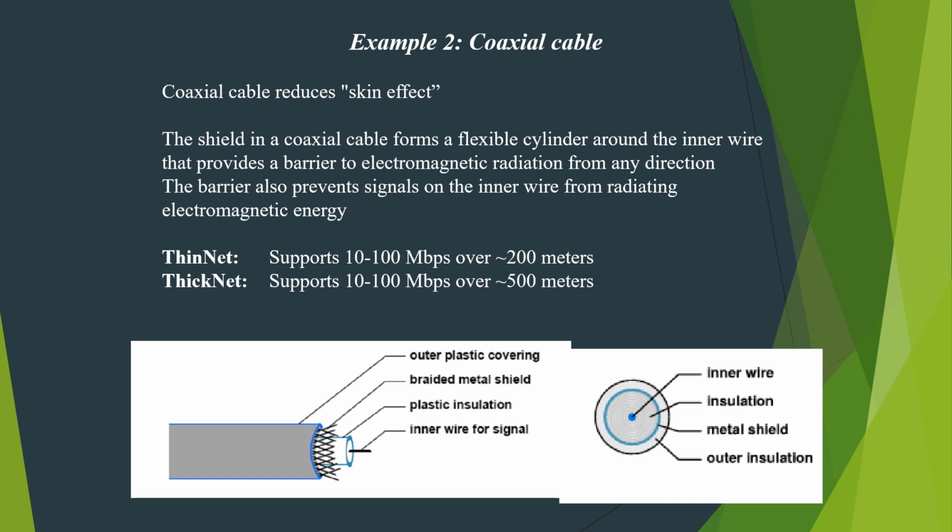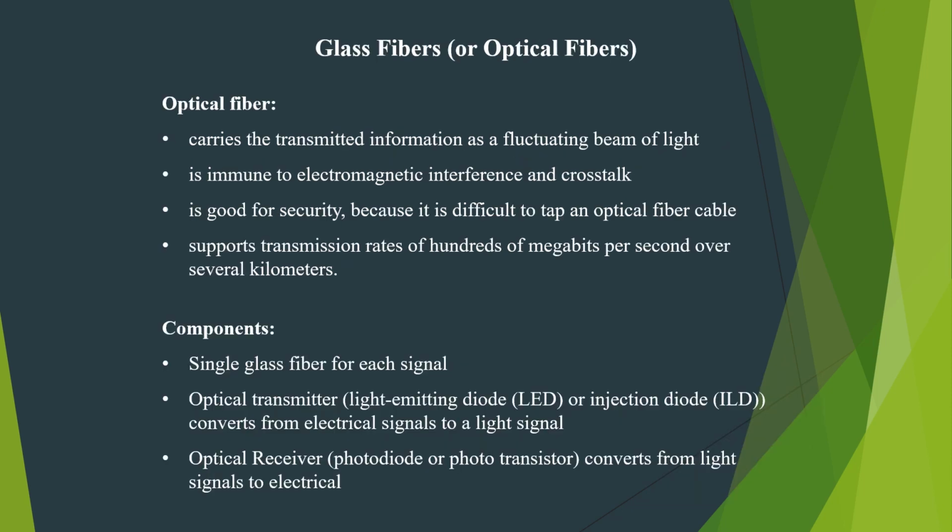And the disadvantages of coaxial cable are that distance is limited and the number of node connections is limited. Proper connectors and termination must be used. An application of coaxial cable is in analog and digital data transmission. We also use coaxial cable for telephone networks, Ethernet LAN, and in cable television networks.